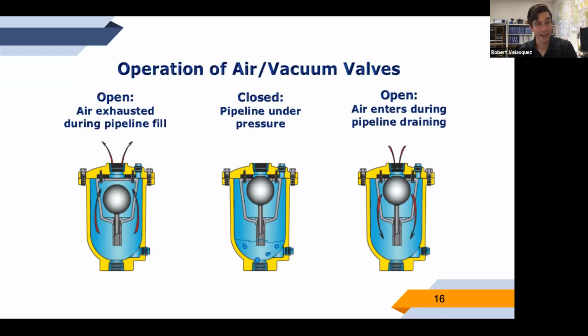So anyways, with air vacuum valves, you've got this ball on a rod so that it's pulled down by the force of gravity when there's no water in there and there's no pressure. Then when you start up your system, air can escape out of there, and it provides a way for the air to get out. When water comes up in there, it'll push the ball up, and the ball itself will seat against that large orifice and close it.